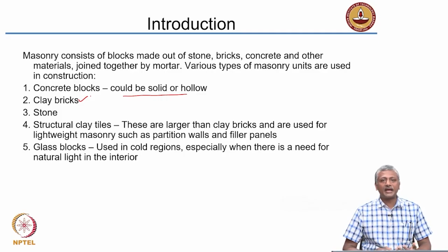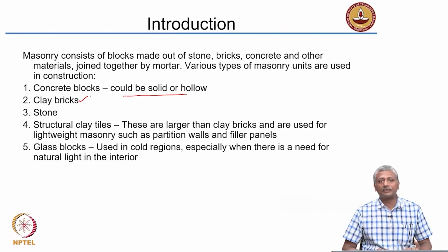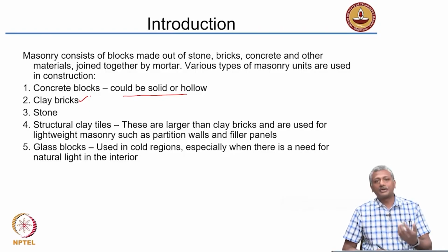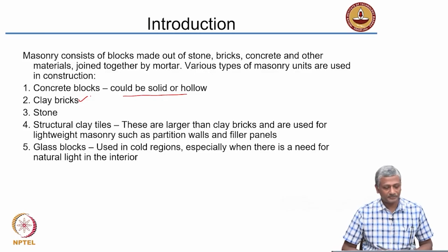Stone, of course, has been part and parcel of our heritage monuments. Even today, some of the modern structures that are coming up, which are not made with concrete or reinforced concrete, are being made with stone. There's a lot of stone structures still being constructed. The difficulty again is obviously getting good quality stone, because for stone structures you need stones which are of fairly large size without any defects, and sometimes that becomes very difficult because these are naturally mined, and in many cases there may not be enough good quality stone available.